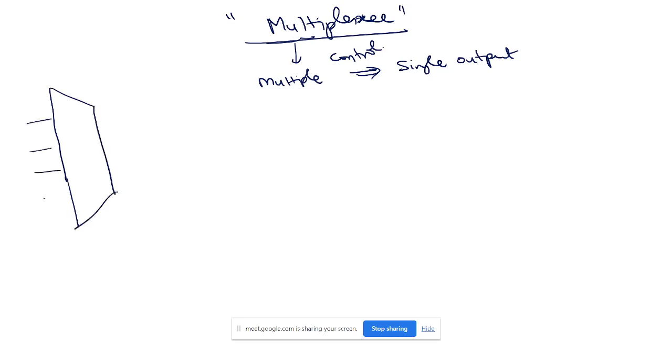Let's say I'll take a 4-input multiplexer, and this is controlled by 2 pins. That is enough, no? How is it efficient? Because if these two are 0, then you pass this input to the output. These are control signals, these are inputs, and there is only one output. Only one input you can pass to the output, right? So you pass this I0 pin, let's say for 0 0. What is this 0 coming from?